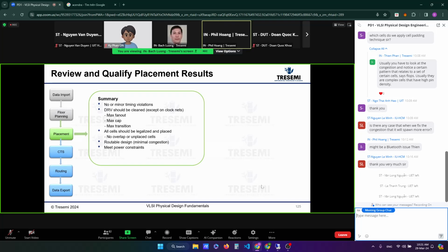Yeah, so as you know, when you analyze timing, you usually have a lookup table with a cap and with the slew rate, right? And you have data, the delays, in between a range of slew rate and a range of caps.